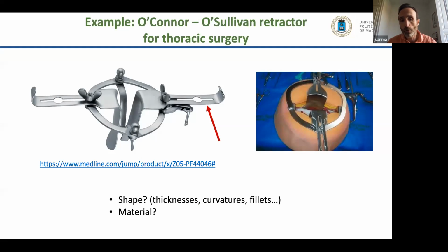Okay, so what I'm going to do first is create the geometry. I'm going to create a spine in CATIA. So I'm going to try to create a line that is something like this. And on this spine, I'm going to create some intermediate sections of the surface. So I will create a curved section here. I will create a straight section here and here, so that I can interpolate a surface, having the surface cross sections controlled by the intermediate lines I have drawn. So you will see we have a surface with a variable curvature.